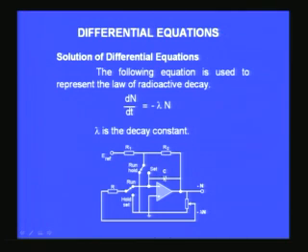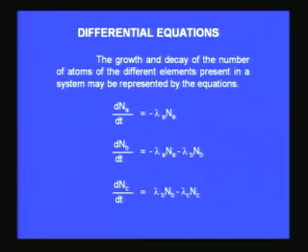Therefore I can apply this, and thereby I will get minus, if I use a potentiometer and take some minus lambda times the output voltage, minus lambda N, and apply it to the input here, so you find the equation becomes satisfied, minus lambda N given at the output, and that will be what you get out of the differentiator. And so dN by dt is equal to minus lambda N is implemented here in a very simple fashion using one single op amp. You can also complicate the scheme by having the multiple decay.